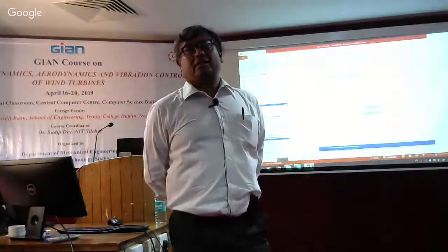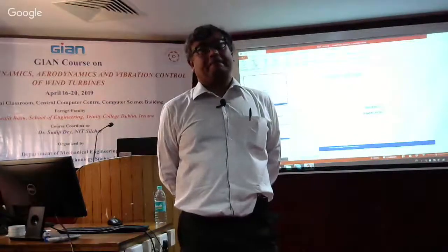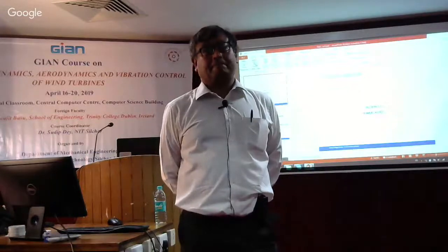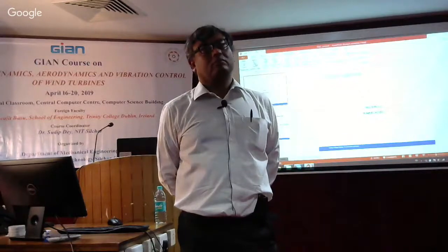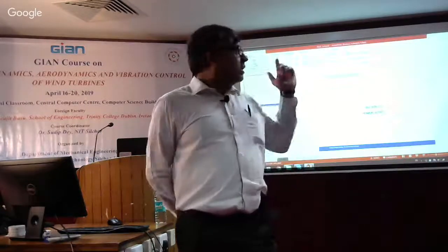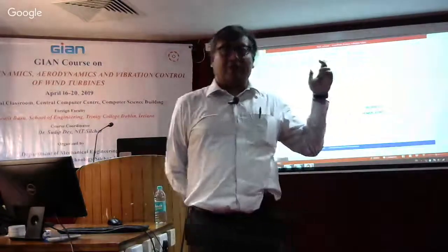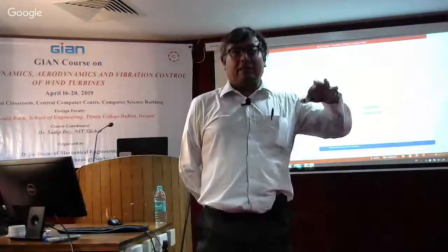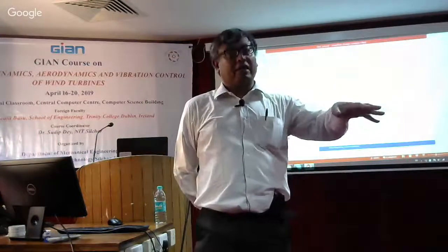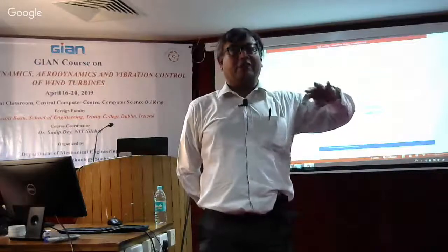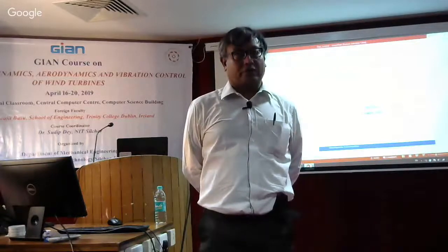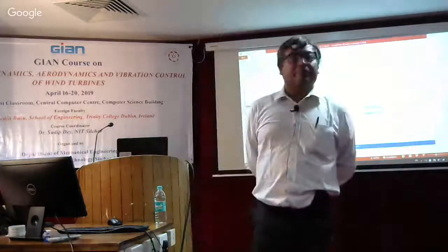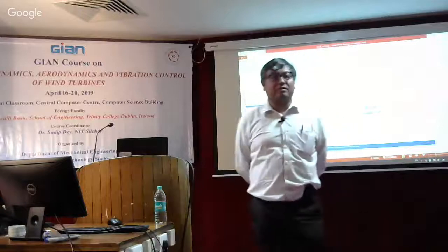So what you're asking is how close it should be. For example, we have some data at a particular location, and we don't have the exact data at the location where we would like to install. How close should this region be? I showed that the mean speed variation is a function of the terrain and surface roughness. So if you have a similar kind of terrain and surface roughness, you expect to have a similar kind of wind profile. So you can use those for your calculation.